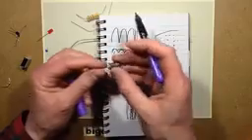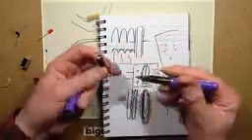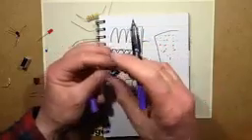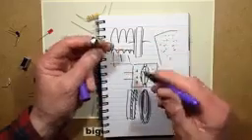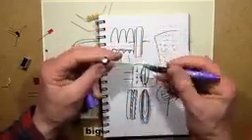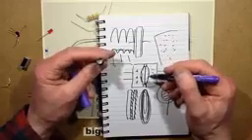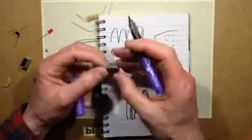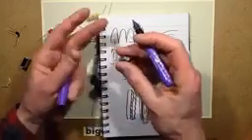However, that's more of an issue with modern electronics, because whereas in the old days, these capacitors only had to deal with like 100 Hertz or 120 Hertz, just mains frequency rectified. Nowadays, the capacitors have to deal with the output from switch mode power supplies, which is like thousands of hertz, tens of thousands of hertz, and it means that they actually heat up and they dissipate more energy.